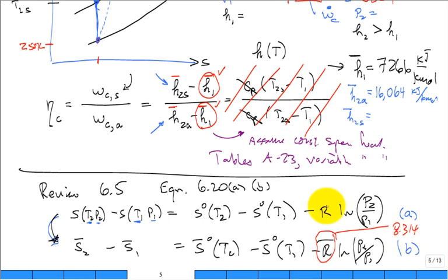All right. Hey, what's this R versus this R bar? Are they the same? Nope. What's the key moving back and forth? Molar mass. What's the molar mass of nitrogen? 28.01, and that's somewhere in our tables, in the appendices. All right? Just like R bar. You don't have to memorize it, but you should know what it is and how to find it.